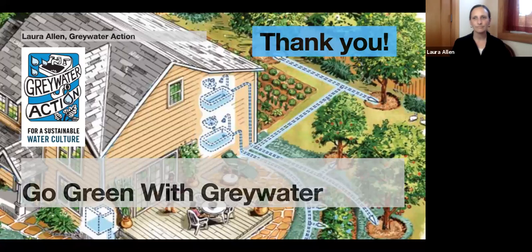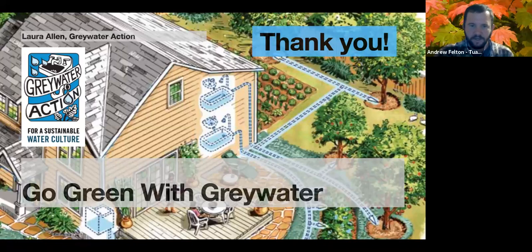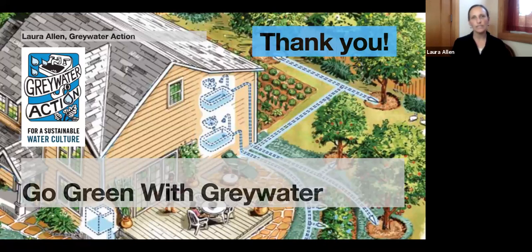Mm-hmm. So most of this person's water comes from the kitchen sink. Are there any special considerations outside of correct soap and no salt? So kitchen sink water is gunkier, it's greasier, much more prone to clogging. It is allowed in Oregon. Some states don't even consider kitchen sink water Greywater, like California, though hopefully that'll change someday. I think it's a code issue, because clearly kitchen sink water is different than toilet, which some states put kitchen with the toilet and call them the same thing, but they're clearly different. In Oregon, kitchen water is gray water.